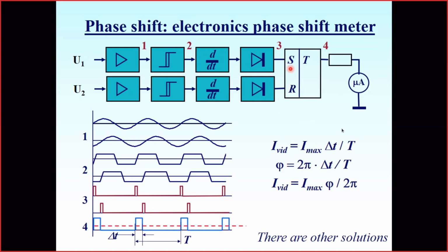So if we put it into the 1 state by putting S to 1 and then drop S back to 0, the trigger continues to keep this 1 on the output. If we now move the R input to 1, the trigger drops to 0. We move R back to 0, the trigger remains in state 0. And we may several times increase R to 1 and drop it back to 0, still the trigger remains in state 0 until we put the 1 on the S input.